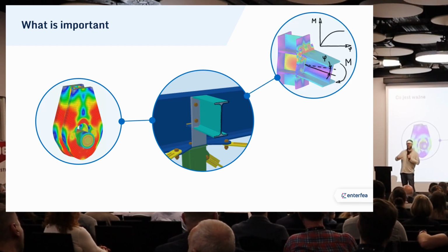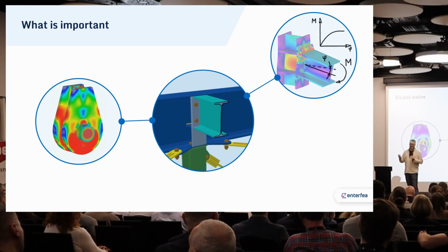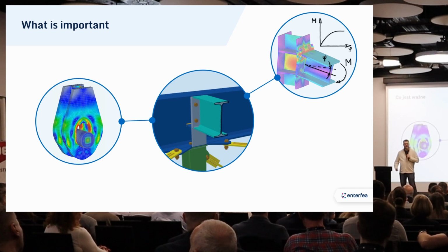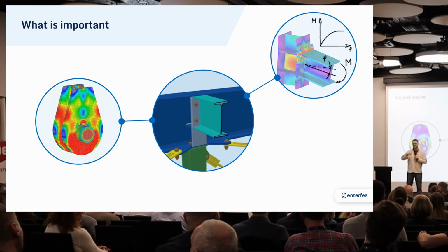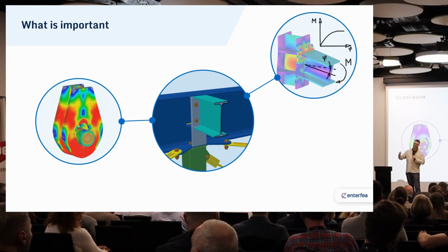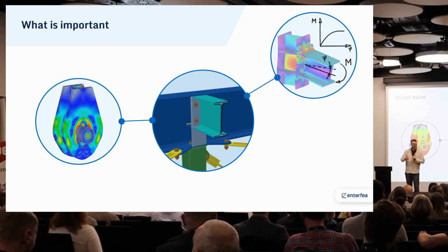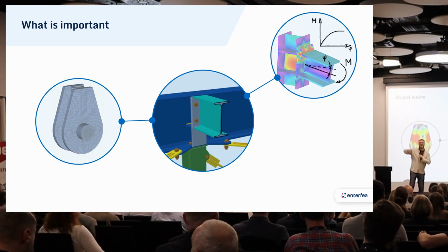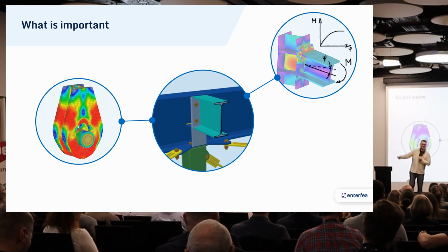However, we cannot forget about connection rigidity. It's important, especially since when you are strengthening the connection, it's very likely that you will also increase the rigidity of the connection along the way. It's relatively difficult, if not impossible, to strengthen the connection in such a way as not to increase its rigidity. Of course, with increased rigidity, the connection starts to transfer higher and higher bending moment. Of course, you can strengthen it in a way to make it possible for the connection to transfer the moment.